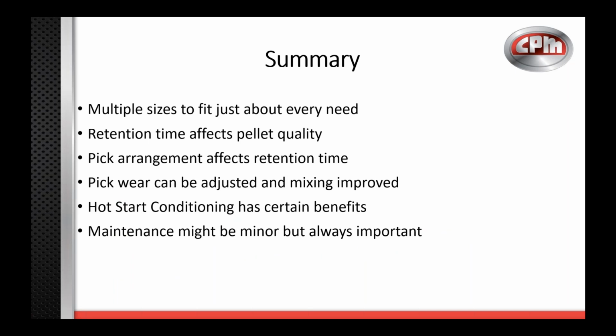So to sum everything up here, we have many different sizes of conditioners, hopefully one to fit whatever your need may be. Keep in mind that retention time could in turn affect our pellet quality, our product quality, and also how your picks are arranged will affect your retention time. We want to keep an eye on our picks so we don't outwear them, because they can be adjusted and replaced easily, and we want to best improve our mixing.